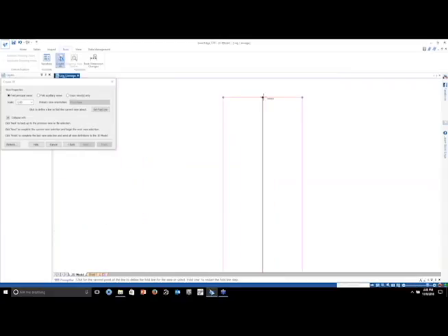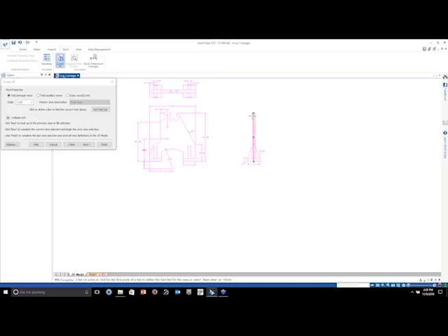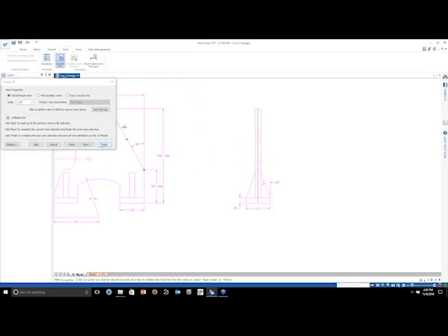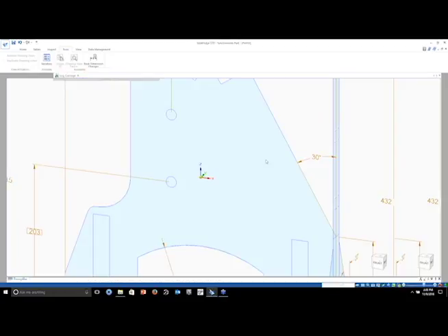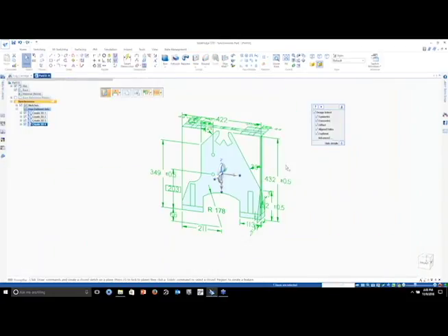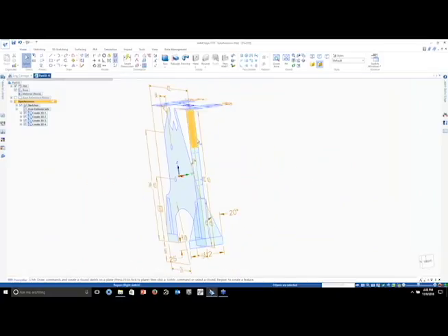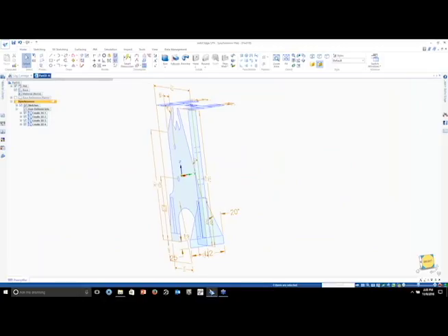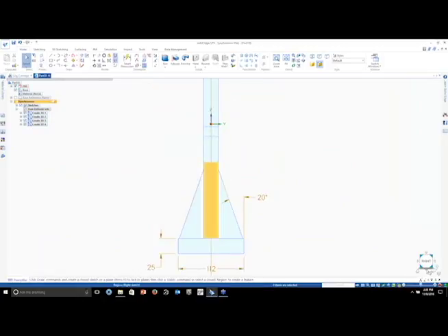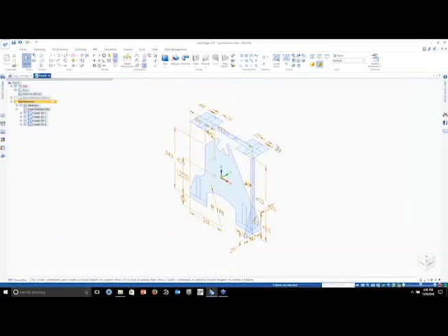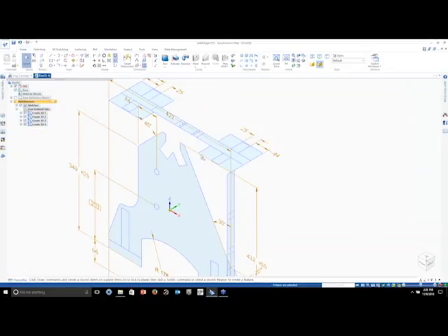So if I go to my right side view, you can see I'm symmetric about the coordinate system. On my top one, it lined it up on the edge like it normally would, but I can manipulate that afterwards if I need to. I can come over here and hover through, and now that turns orange, so I know that's the sketch that I need. Again, remember the steering wheel gets placed on there, so I'm just going to move my steering wheel to a particular snap point on here. I'll just find a midpoint. So on my tools, I'll just say, give me a midpoint.